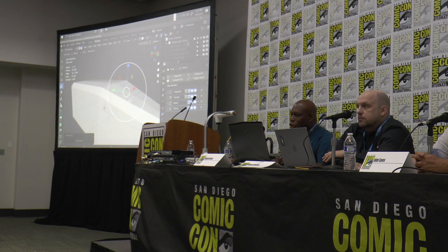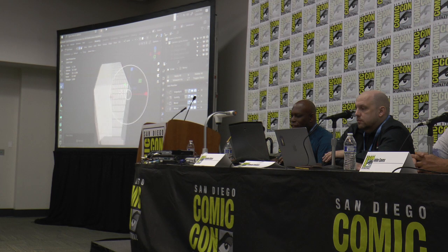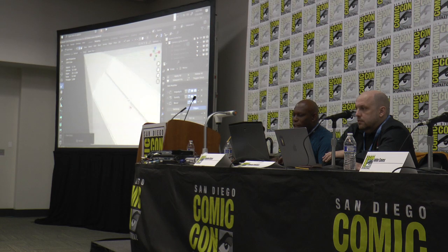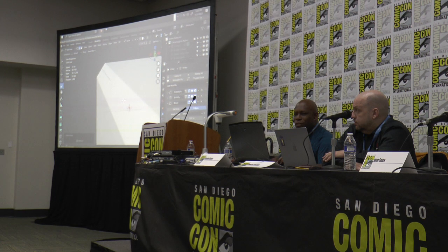All right? So if I turn this around, I'm gonna add one little extra adjustment. I'm gonna go over here to the bevel. And I have segments here, because I want this to be a lot cleaner looking in terms of a grout. All right, so I'm gonna say the segments, I'm gonna go 1, 2, 3, 4. I notice that 6 sometimes looks kind of nice. And look at that. Nice, clean edge.